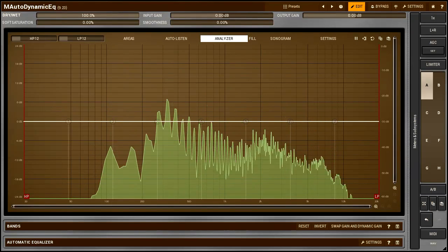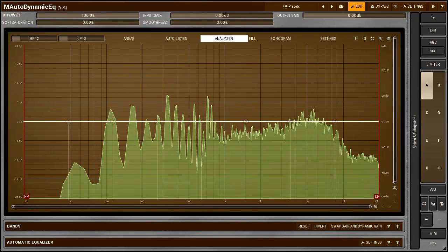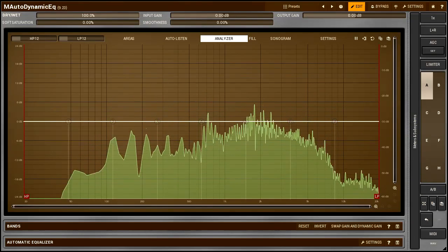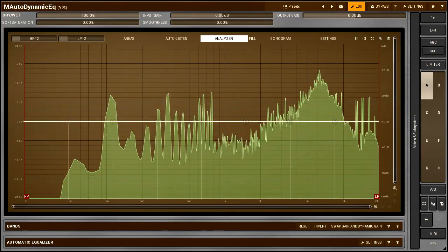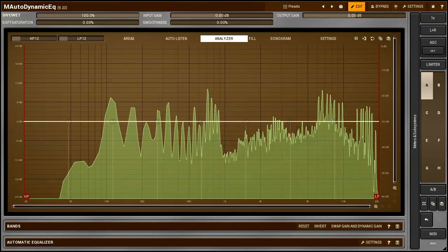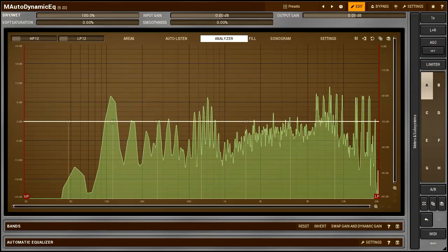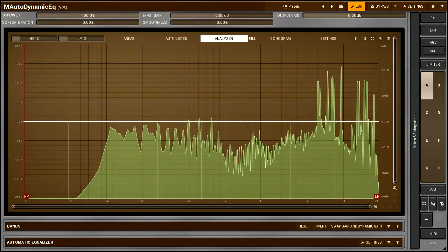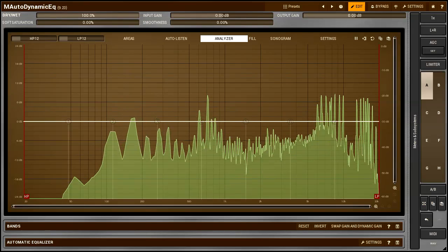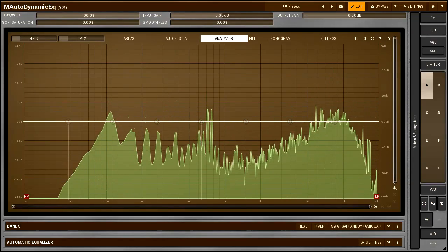It represents a frequency response of an incoming signal. It's achieved by utilizing the Fast Fourier Transform Algorithm, or FFT in brief. I'm going to omit all science and just mention that this algorithm breaks a signal down into sine waves with particular amplitudes and phases. And this is what these vertical peaks represent, the amplitudes of those sine waves over a frequency range.